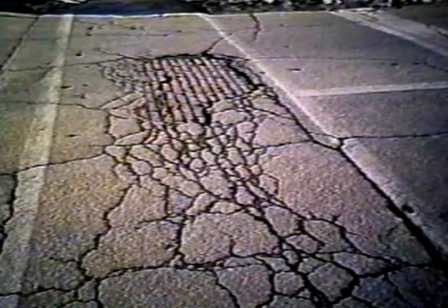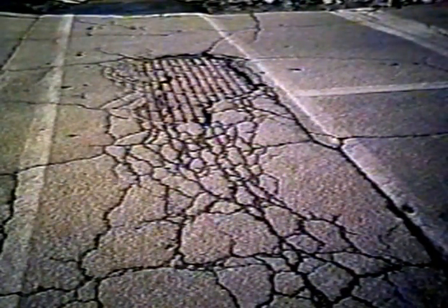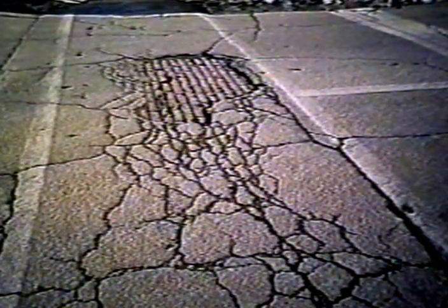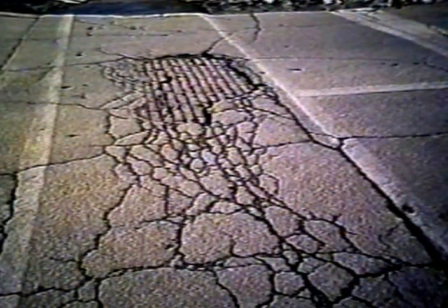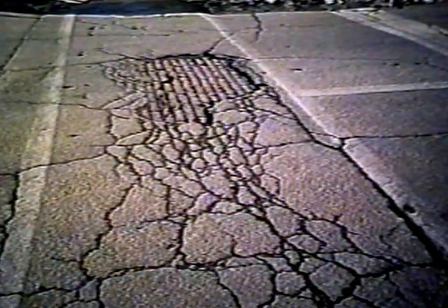Here's another example of reflective cracking. If you look at the bottom part of the picture, you see what you might think is alligator cracking. But when you look in the center part of the slide, you can see, in fact, it's an overlay over a brick street. I guess it's a good example of the limitations of simply looking at the surface. You can learn an awful lot, but you don't know everything. If you have a history of the pavement, you know how it was constructed and what's under the pavement. That, along with your interpretation of the surface distress, goes a long ways, I think, in helping you understand what causes these distresses and picking the best repair or rehabilitation treatment.